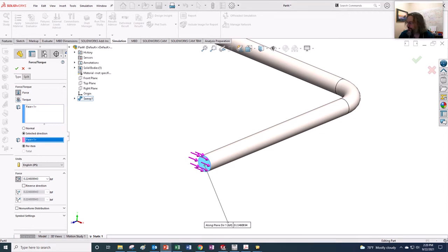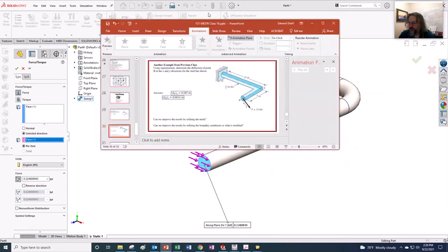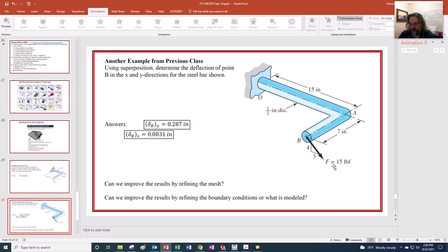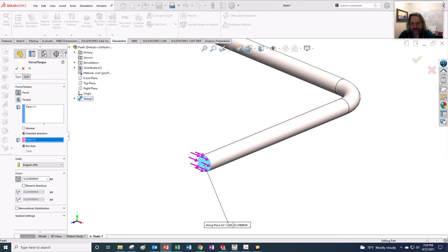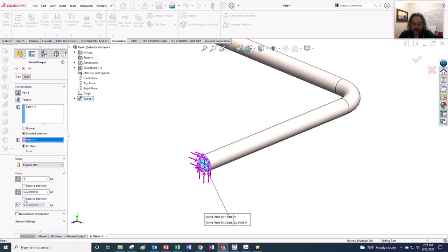And in here, I think because it was a 3, 4, 5 in this direction right here, it'll be 9 in the x direction and 12 downwards. So this goes 9 pounds. And in that direction, whoop, it's going up when I want it to go down. We go 12 pounds. We're good, we're good.